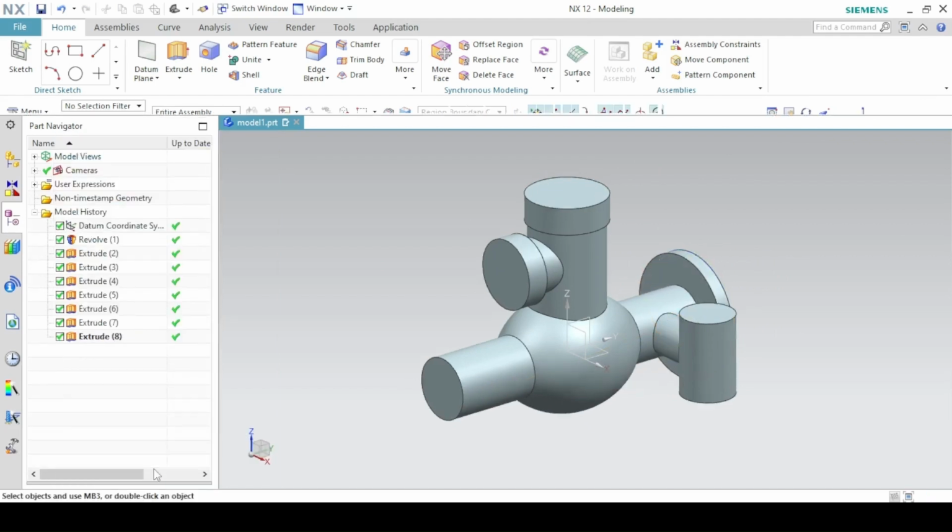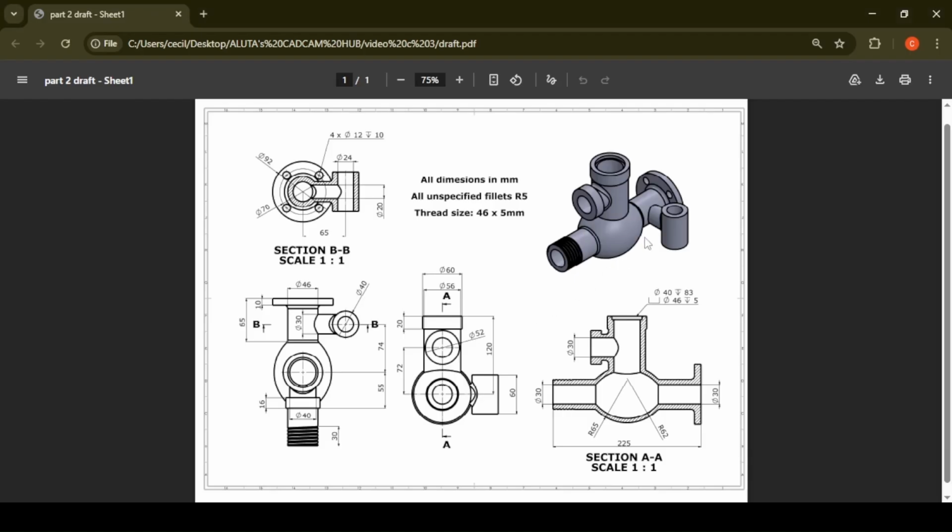okay. Now you're done with adding material. Next, you're going to remove material. First off, we remove this overall feature here. The same way we did the revolve, this time you're going to revolve and remove material.